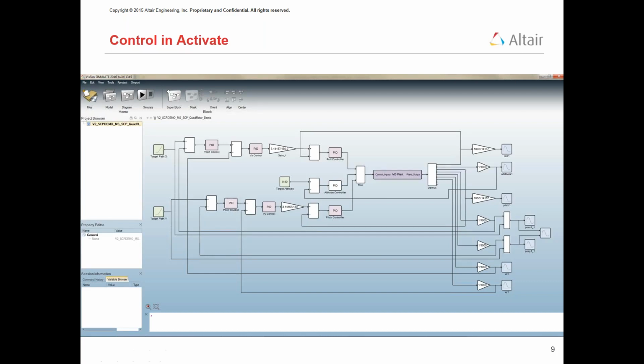So the control system has a difference. PID controllers can be set up with experience, like you can do a trial and error method. You should know the controls knowledge on how the system behaves, like you should know the Bode plot, Nyquist plot, how the system response behaves. And based on the experience, based on the response, you can try to fix your PID values. And if you know the formula, you can put in an actual value. As a domain engineer, you have to know what exactly we're going to control. Control system blocks are there, but we have to put in accurate control based on the different domain applications.